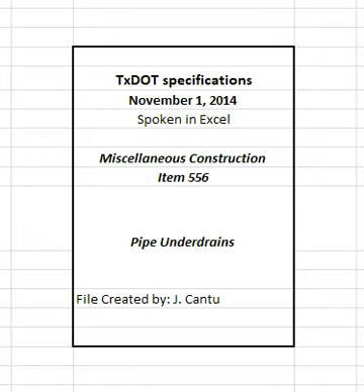Place filter fabric in the bottom and sides of the trench in areas to be drained before placing pipe or filter material, as shown in Figure 1. Provide enough width of fabric to overlap on top of the filter material. Center perforated pipe in the excavated ditch with the perforations below the horizontal axis. Join the pipe with appropriate couplers if required.